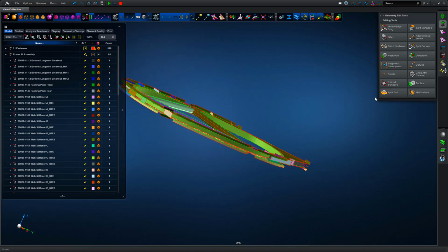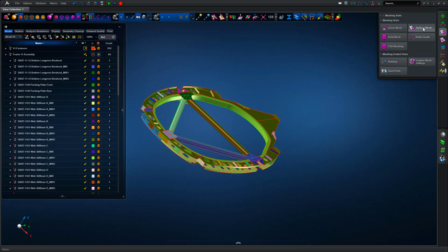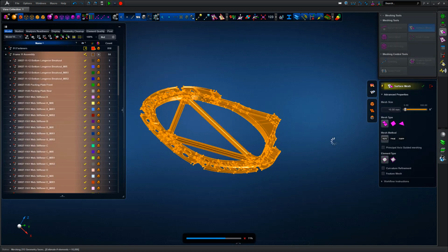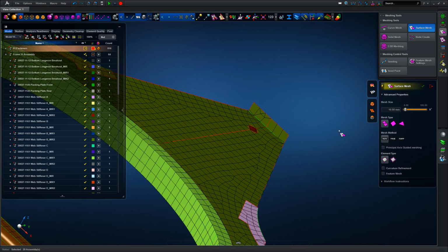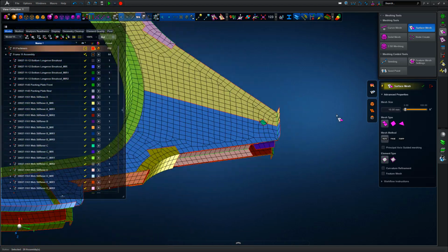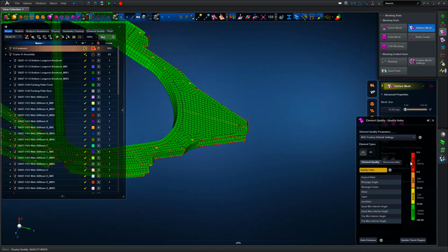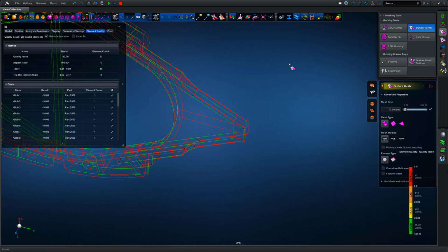So again, another step towards cleaning up the geometry to give us the resultant target geometry for meshing. Once we've done that, we can surface mesh at 10mm element edge length with the auto meshing algorithm turned on, and on a quick look we can see that's a reasonably appropriate element size for this type of structure.